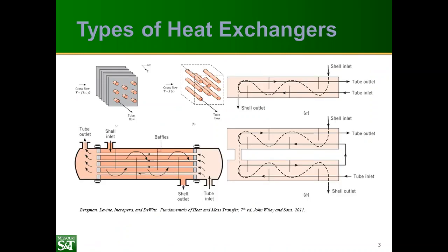Now, one of the most common types of recuperators or heat exchangers is the shell and tube design. It's actually the most common in industry. They don't usually have the highest effectiveness or efficiency, but they are very cheap to build and easy to maintain. Think of steam generators in pressurized water reactors, liquid metal fast breeder reactors, high temperature gas reactors, and so on; these are all going to be variations on this design. Sometimes they include baffles, as you can see in the figure, and that helps to mix the fluid and improve the total heat transfer.